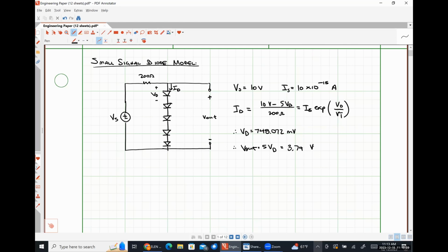So resistance wouldn't really be the right thing to use when we're talking about a diode, because the slope of that curve is not a constant. The resistance is going to change depending on where we're at along that exponential curve. We'll talk about linearizing that relationship here in just a couple of minutes.